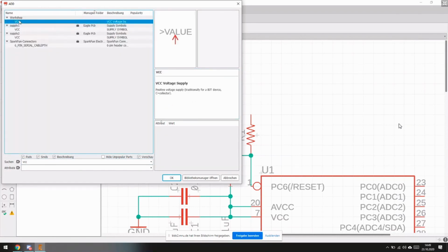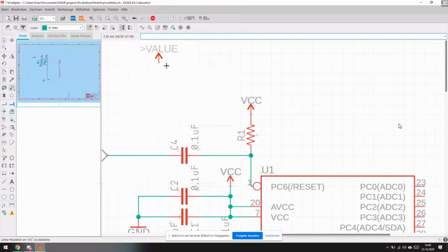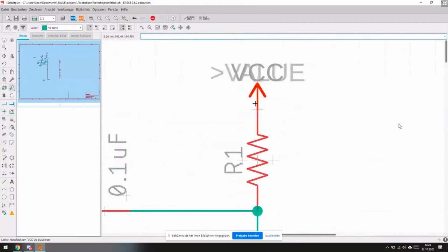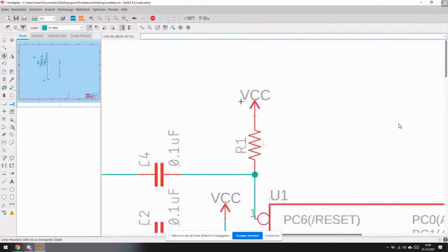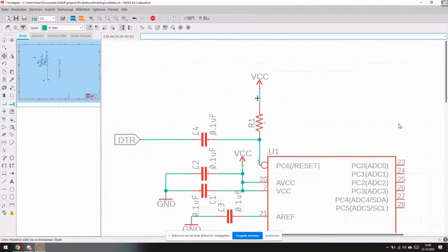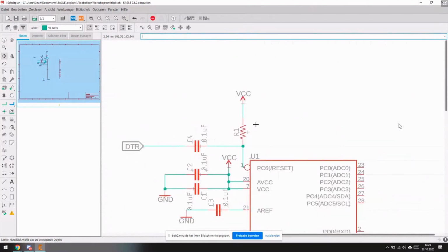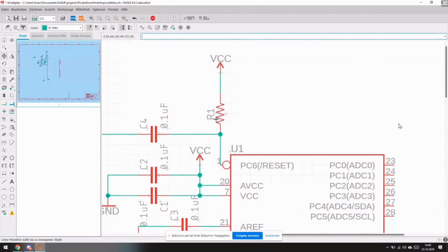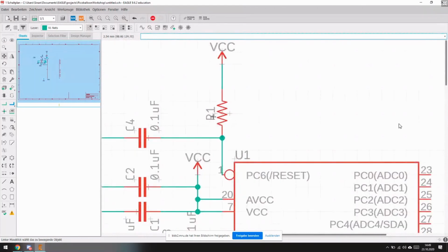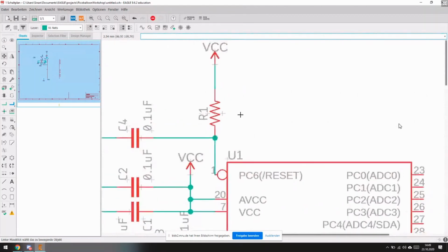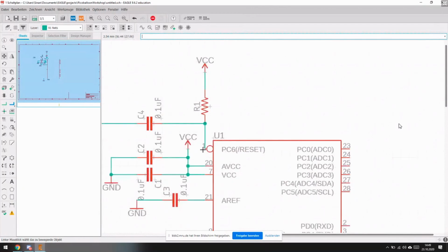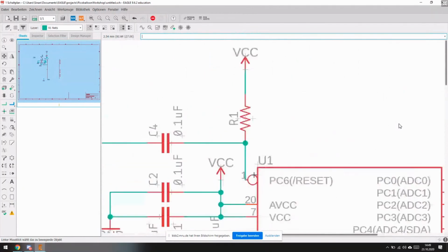Choose it, then connect it. You can also connect things directly. This is not as tidy as one would think. I will move it up there so we just see the green net. Okay, great. So basically, as I told you, because the input is inverted, the pull-up resistor, like the name implies, pulls the voltage up. So it's plus 5 volts every time, and the microprocessor gets a digital high as the input.